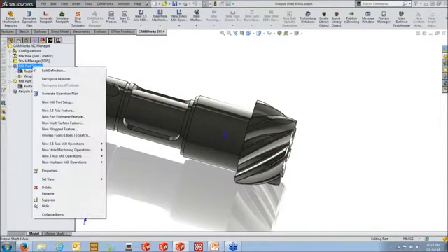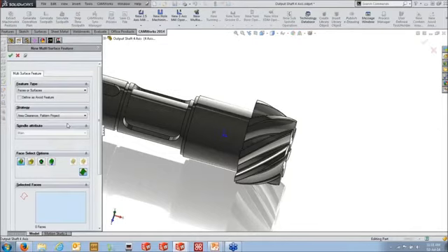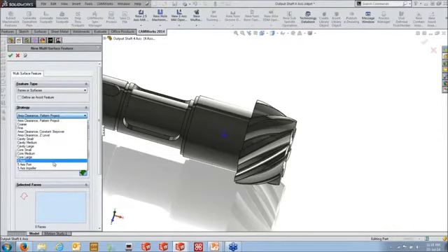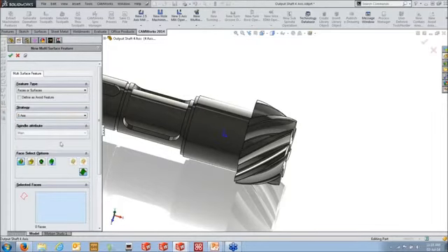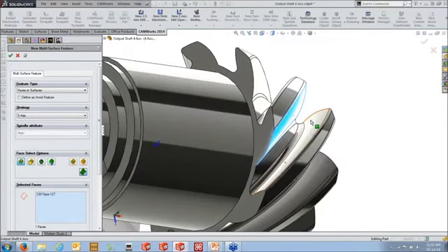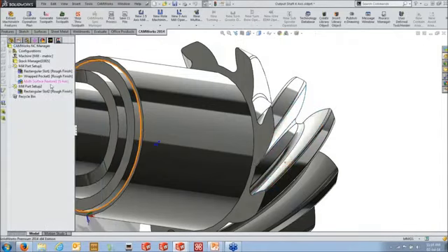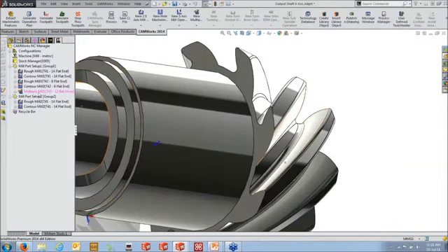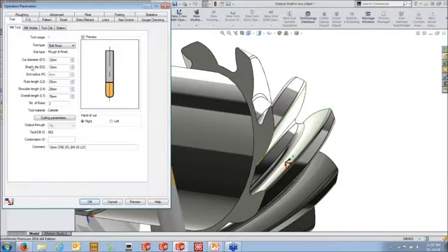So we go in, we use our multi-surface feature this time, and I'm just using one of my default strategies here. I'm going to use say the 5-axis strategy, and we'll use the faces to define a boundary for the actual toolpath to rough between. So in this case, I'm just going to use the 2 side walls here, and that's going to set the left-hand limit and the right-hand limit of where the toolpath will generate between. We'll generate our operation plan. We'll get our multi-axis mill here, and then we'll go and set up some parameters.